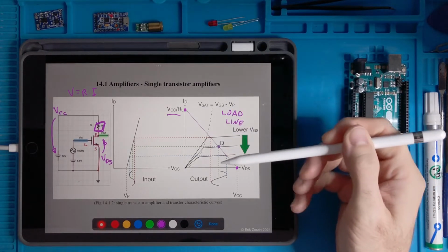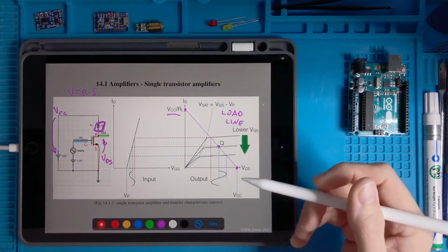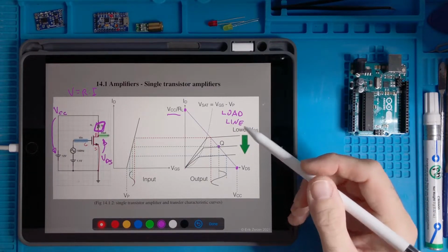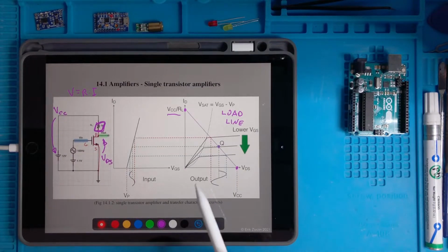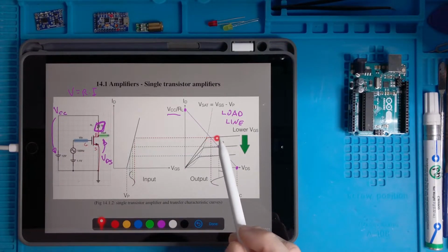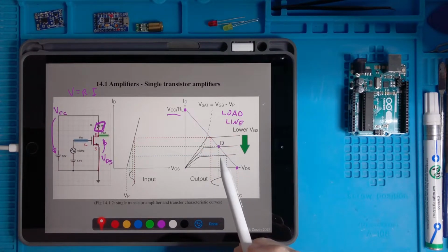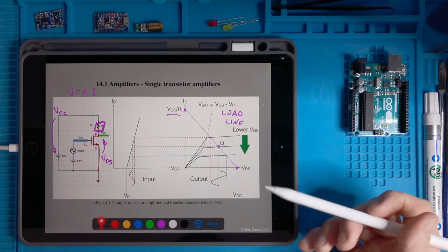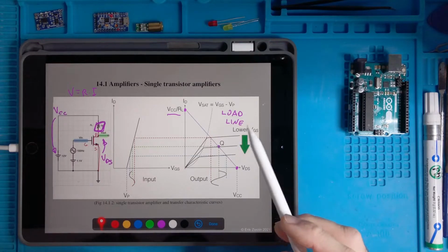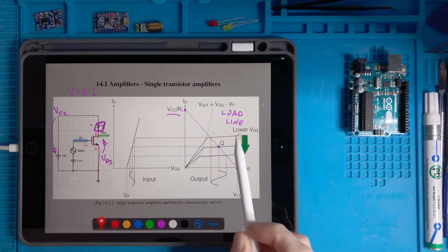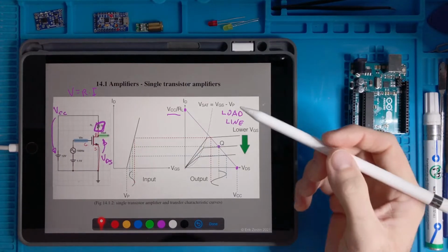Okay, on the load line. So now we can do one thing. We can take advantage of this region, which is called the saturation region, where these curves are flat and parallel to each other, almost, let's say. It's the job of the manufacturer of the transistor to produce such kind of device for which the curves are like this in this area. We will see why in a while.